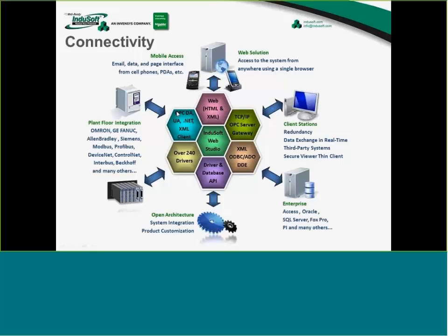We can also talk as an OPC client to lots of different devices. Also get information from the web, and then in addition to being a client on OPC where we can talk to anybody else's third-party OPC server, we can act as an OPC DA server as well and have anybody else's client come in and grab tag information, tag values directly from us. We can communicate to databases, and then we also have a driver toolkit and a tag database toolkit if you want to write your own interface to this information.